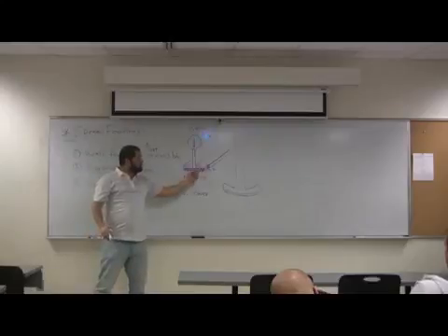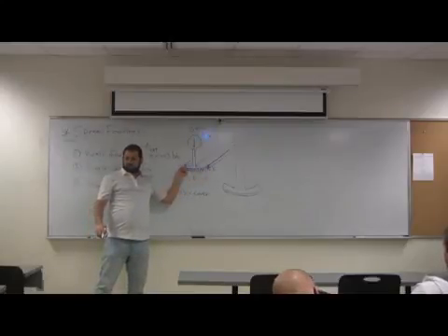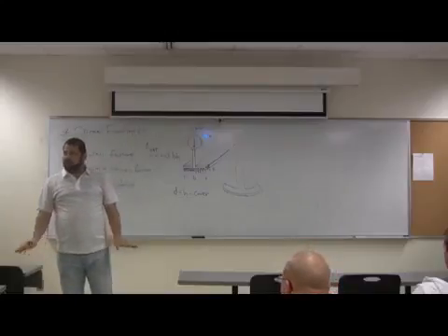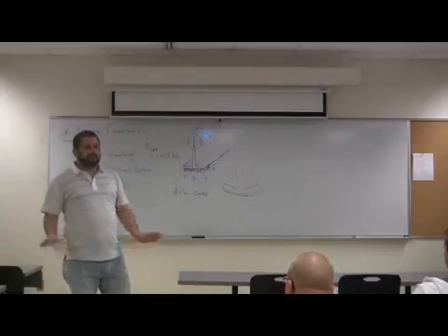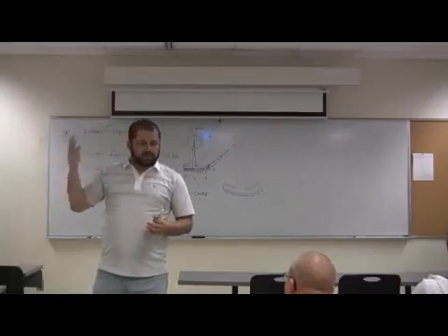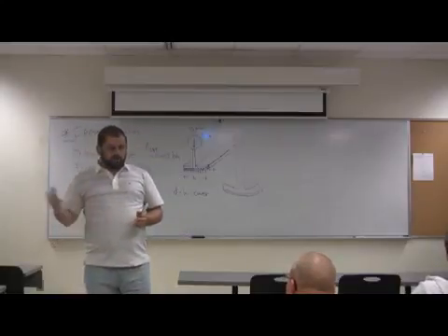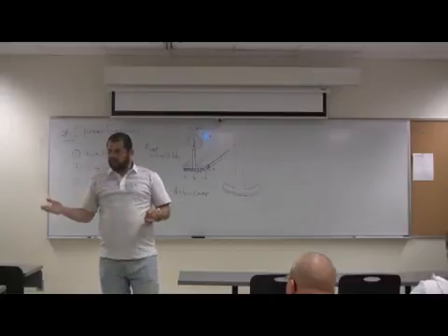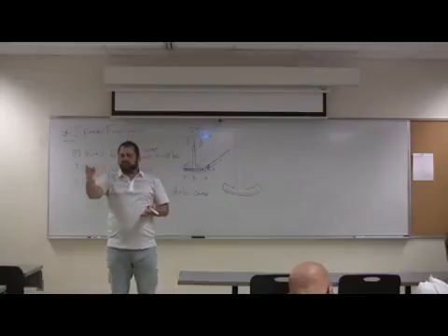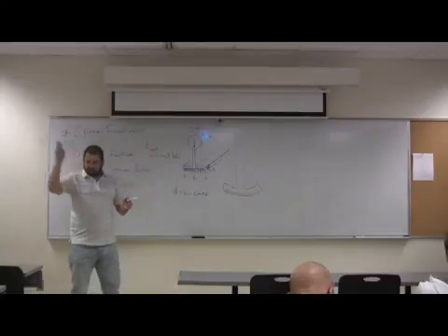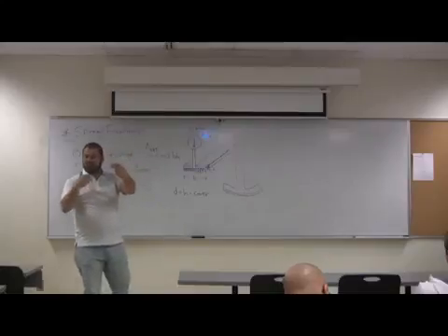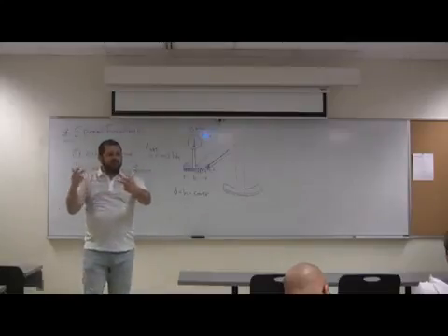What's rho minimum for this one? Is it rho minimum for beams? Remember rho minimum for beams, guys? Who remembers rho minimum for beams? It is 3 square root of f'c over fy, or 200 over fy. For f'c equal 4 ksi, you will get 0.0033, right? But it depends on fy. The second value, 200 over fy, when you divide 200 by 60,000, you will get 0.0033.